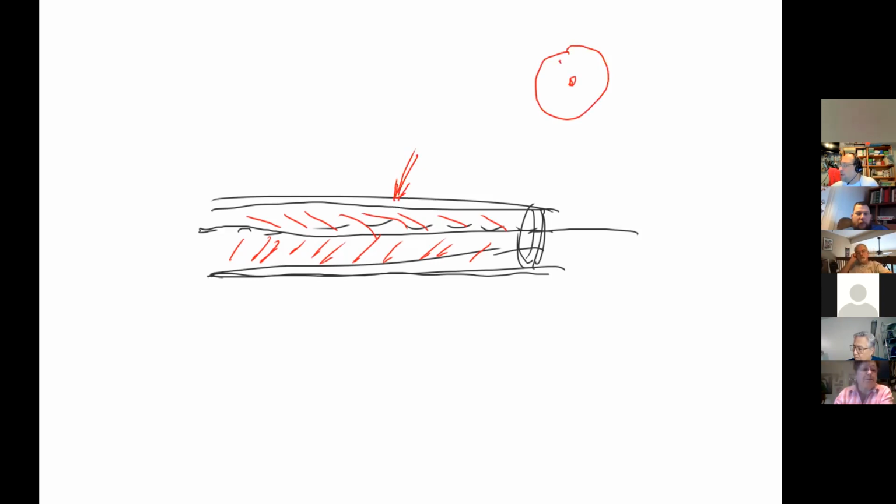One interesting thing about coaxial cable is that if we look at it from the end, it looks like this. So you have the center conductor, and then you have the shield. One thing that's important to note is that the density of current, because they have to be equal and opposite, clearly is not the same on the center conductor as it is on the shield. And in fact, the spacing in between forms a capacitor, because it's basically two electrical plates.